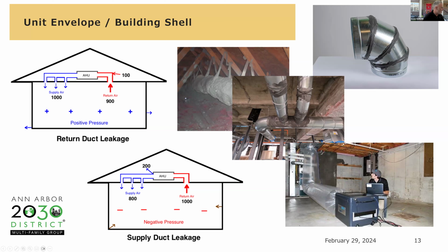It provides a great insulator, it's a great air sealer, and it'll help with condensation issues during the air conditioning season, the cooling season. Then here's the photo in the upper right and the one just down to the left of it. That's using duct mastic. That's applied by hand. It's relatively inexpensive, but it is labor intensive to seal ducts that way.